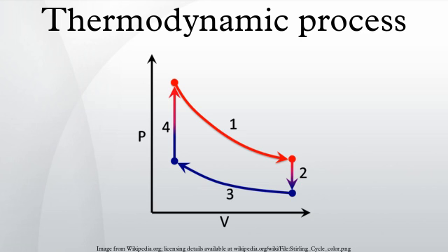An isochoric process is one in which the volume is held constant, meaning that the work done by the system will be zero. It follows that, for the simple system of 2 dimensions, any heat energy transferred to the system externally will be absorbed as internal energy. An isochoric process is also known as an isometric process or an isovolumetric process.